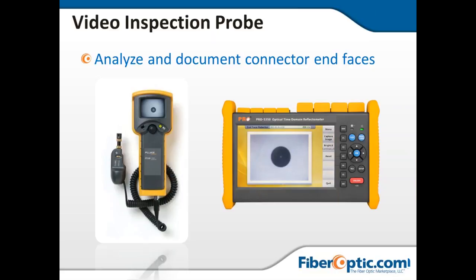Video inspection probes. Here's an example of a Fluke handheld inspection scope that stands alone. But again, if you can build that into the OTDR, what you get is this nice depiction on the OTDR of what that fiber end face would look like, and that's a good indication that you've got a very clean fiber. There's no scratches, there's no debris, there's nothing on that connector end face which would be impeding the performance and cause any kind of result problems.